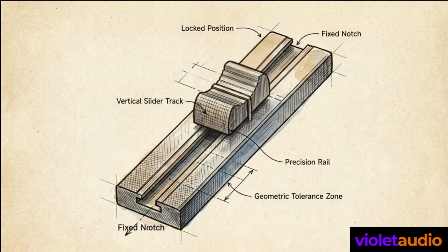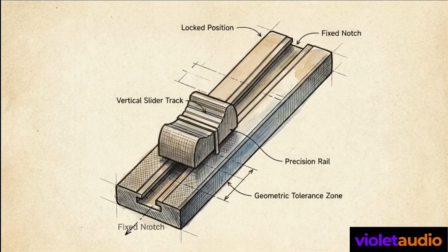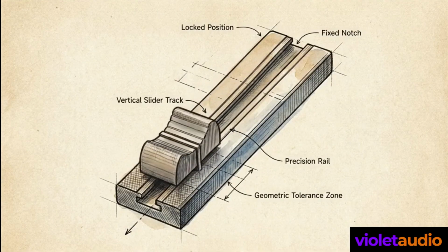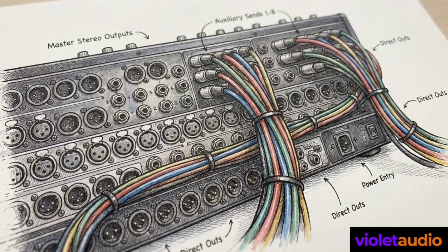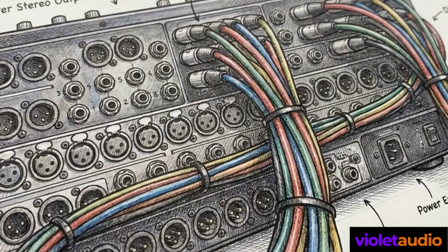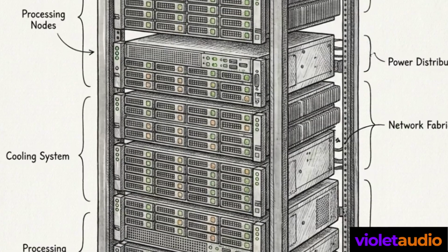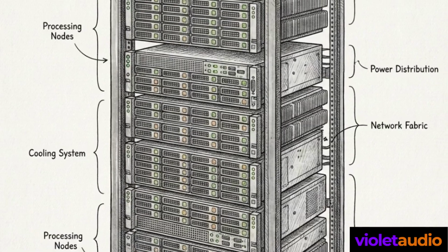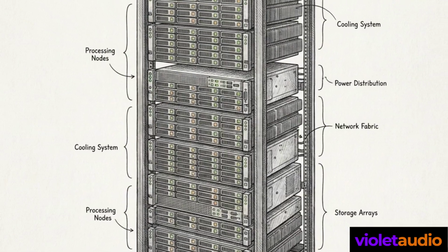Most digital mixing consoles operate on strict one-dimensional routing paths. An operator sends a signal to an output bus, and its position remains static. To create a dynamic spatial environment, engineers typically route these signals out of the console entirely. They rely on heavy external DSP hardware engines, equipped with independent delay taps to calculate physical acoustic movement.